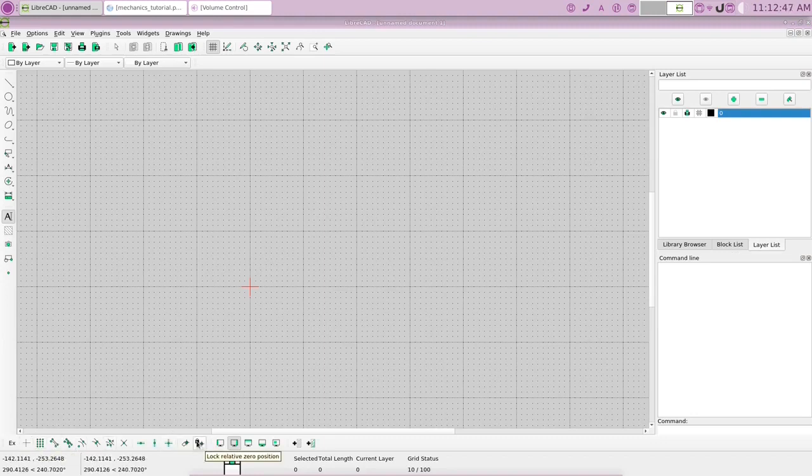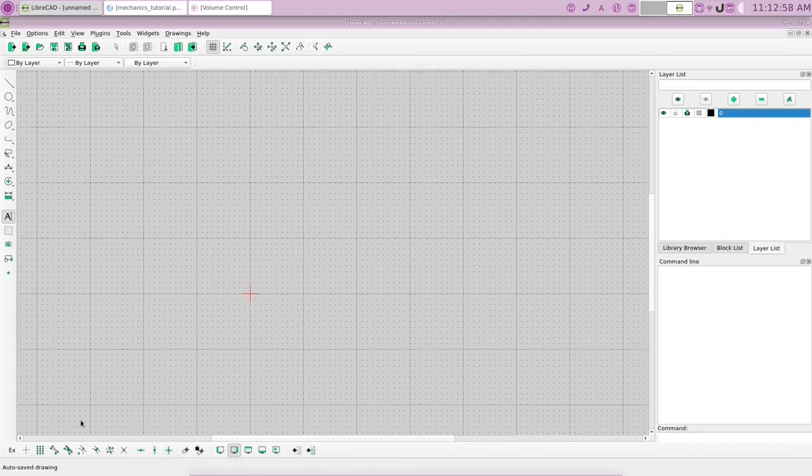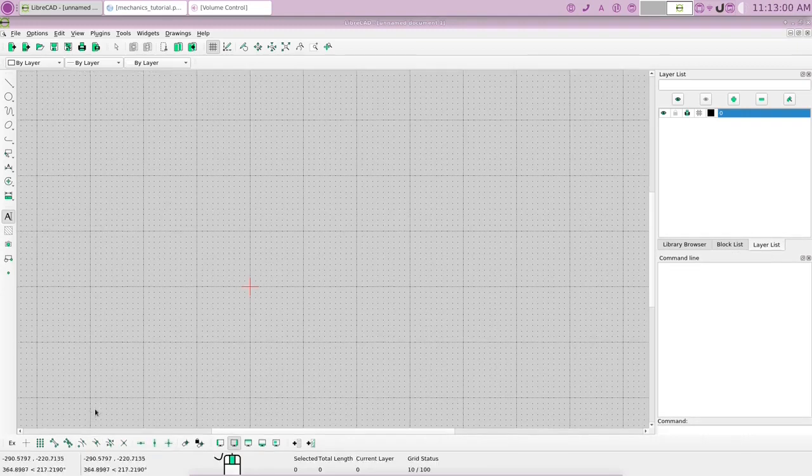You will get used to these snaps, and they will become your friend, because without using the snaps, your line could easily be out, at least the distance of the line itself. By using the snaps, it'll be dead on accurate all the time.